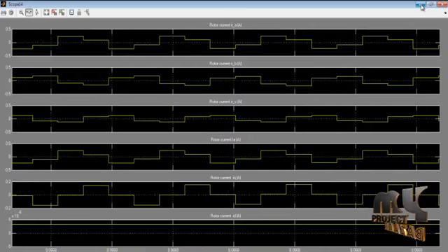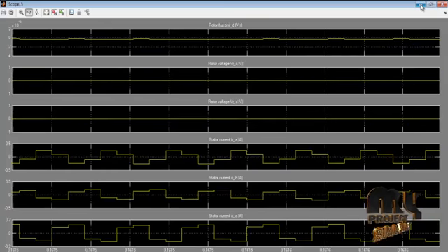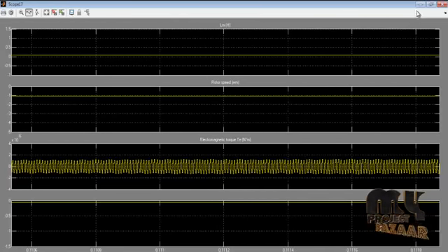Next one is the corresponding motor output used in that design: rotor current IB, rotor current IC, and also the rotor current IA, IQ and ID, that is the quadrature and direct axis currents. Next one is the rotor flux, rotor voltage, and also stator currents IA, IB and IC. And this is the LM, rotor speed and electromagnetic torque, and those waveforms are given here.